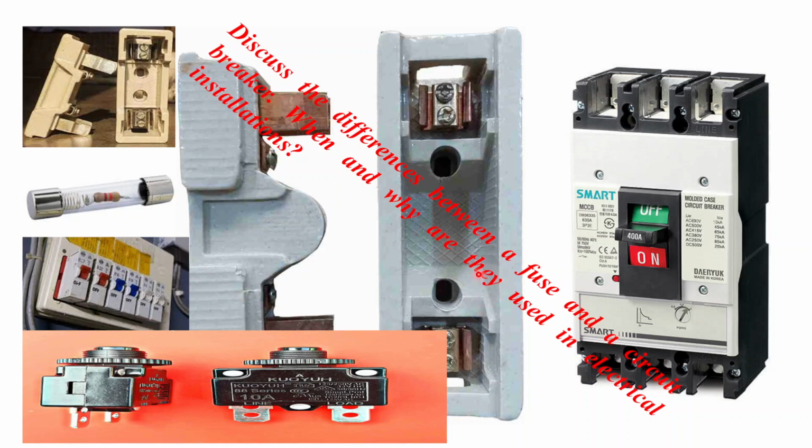The next question is when and why they are used in electrical installation. First we'll discuss fuses. Fuses are typically used in applications where a simple, cost-effective protective device is sufficient and frequent resetting or manual operation is not required. Fuses are commonly employed in low voltage circuits, branch circuits, and appliances to provide reliable overcurrent protection.